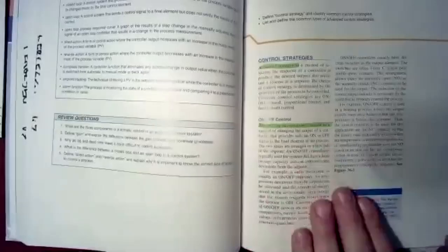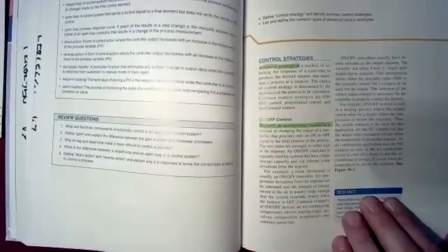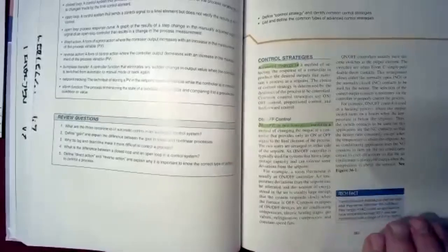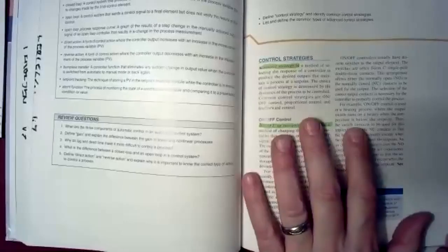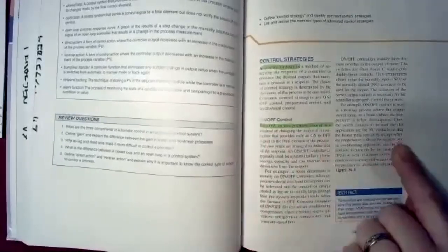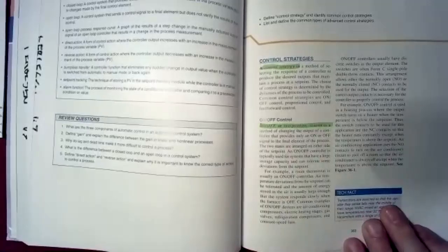There's some furnaces, electrical furnaces, that use the same strategy, but instead of just being always on and then waiting for the temperature to drop and then being always off, they can do on-off sequencing to kind of pulse. So the more pulses of energy applied to the electric heating system, the more energy goes into your oven, and then the oven can maintain its temperature a little bit better than a pure on-off system. So that's a slightly different thing. But when we say on-off control, we're talking about the kind of heating system that your house uses, either heating or air conditioning.